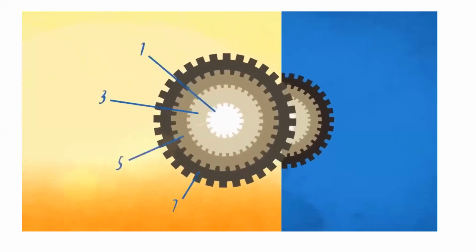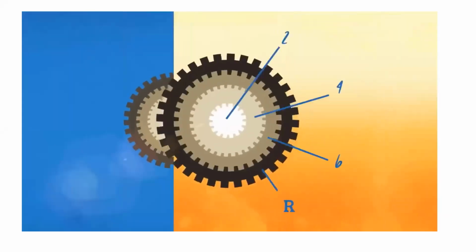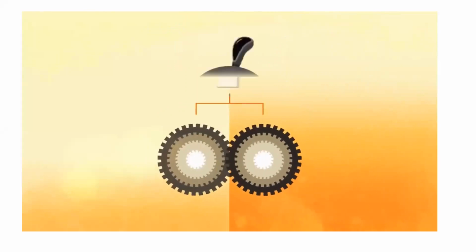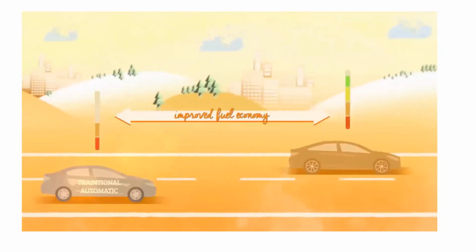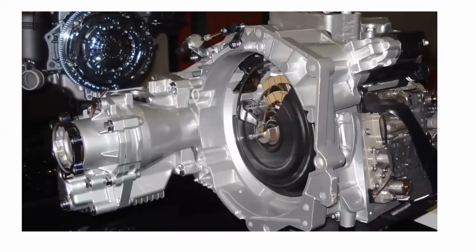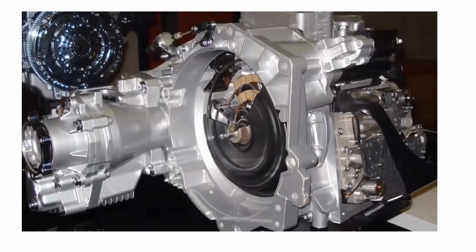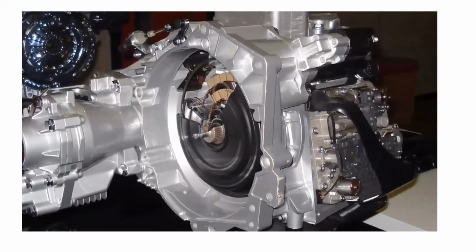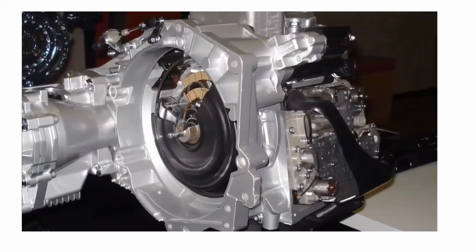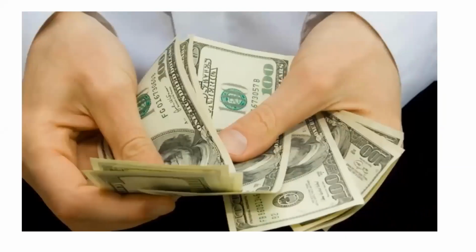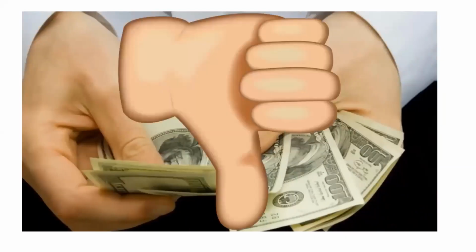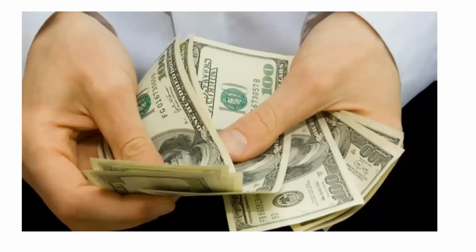One shaft for odd numbered gears and the other one for even numbered gears. This type of automatic transmission provides really quick shifts and also delivers good fuel efficiency. However, since the technology involved in the system is fairly complex and consists of a number of electronic components, the costs associated with manufacturing a DCT is relatively higher, which is also the main reason for its lower level of adoption. Maintenance costs are another area of concern for DCTs.